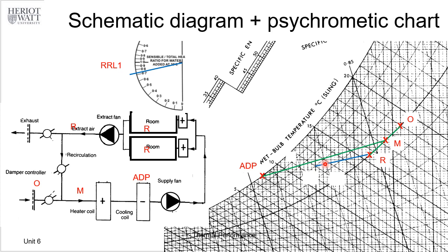And how do we determine where the supply air is? It is according to the regulations. The regulations suggest, as we said earlier, a maximum of 8 degrees lower in summer. We supply cooler air into the room, so it will be 8 degrees lower. For the sake of explanation, again, we assume it is 7 degrees lower than room temperature. So if we draw this line, the dry bulb supply air temperature is here.